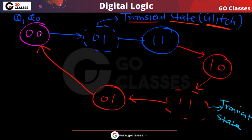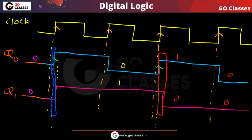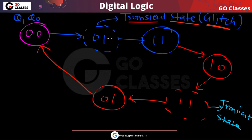From state 00 you should go to state 11. This is your state 00, and from this state you should go to 11. But for a very small moment, this state will come, so that is the reason I am putting it in dots. For a very small moment this state will come, so this is just a glitch. You are going from 00 to 11, but there is a glitch here.